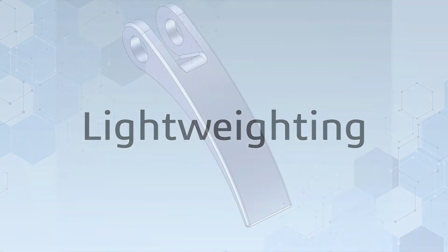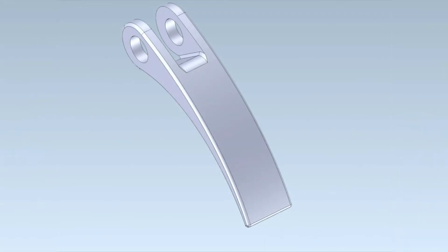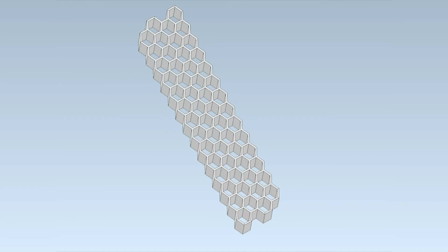What to do? 3D metal printing provides the answer. 3D printing allows the manufacture of lightweight, stiff parts which are impossible to make with traditional manufacturing methods. For a quick-release lever for professional racers, the original lever can be lightweighted by creating a shell structure with an internal honeycomb lattice to eliminate weight while preserving stiffness and ultimately robustness.